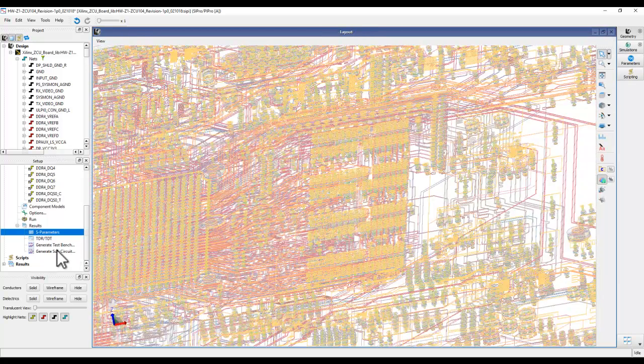And once you're done, you can always create a sub-circuit, go back to the ADS schematic, and stitch the whole end-to-end system design, be it for DDR memories or SerDes kind of channels, finishing the end-to-end simulation and looking at the eye diagram and other quality metrics.